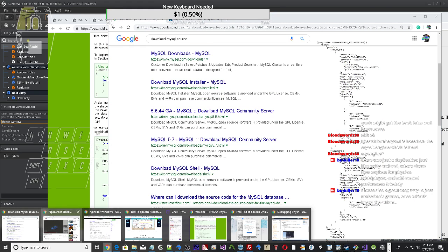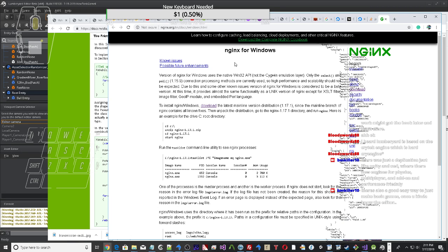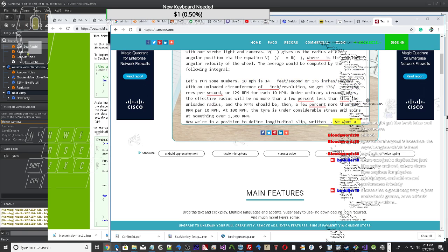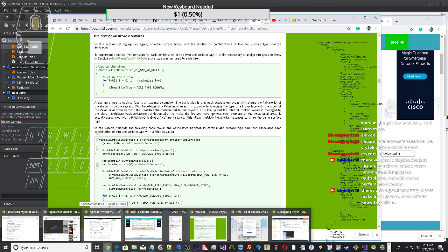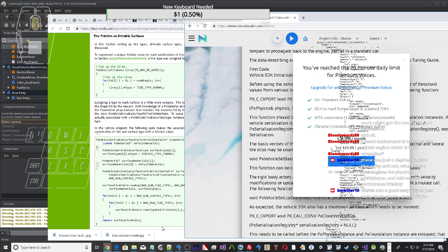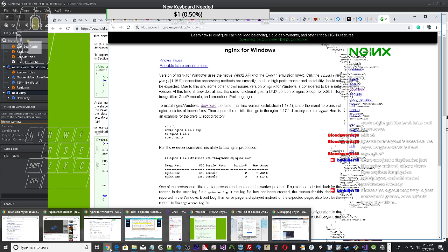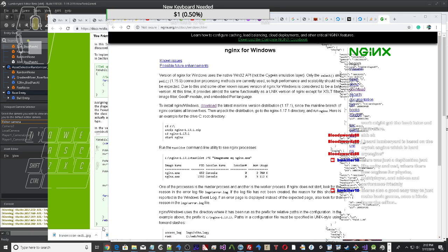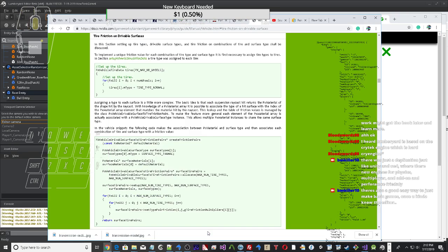Now we're in a position to define longitudinal slip, written κ. We want a quantity that vanishes when the wheel rolls at constant speed, increases when the wheel accelerates the car by pulling the contact patch backwards, and decreases below 0 when the wheel brakes the car by pushing the contact patch forward. Under acceleration, the wheel and tire combination will tend to spin a little faster than it would while free rolling. We already know that, for a given v, the free-rolling angular velocity is, by definition, v/ρ. The actual angular velocity, then, is higher under acceleration.